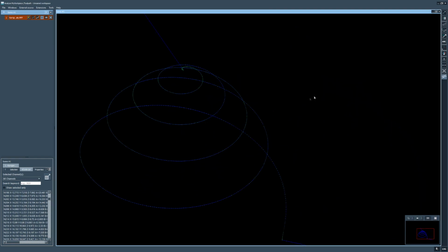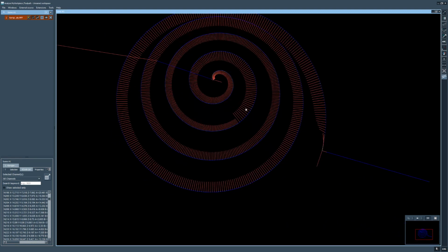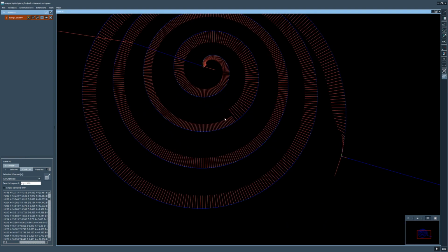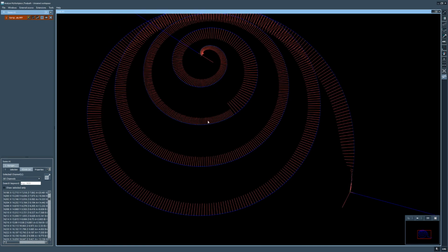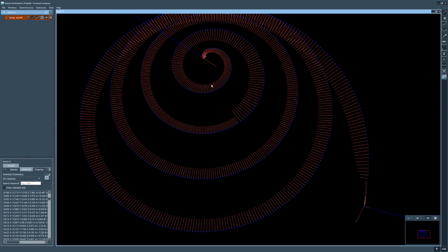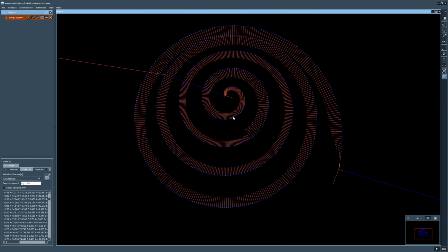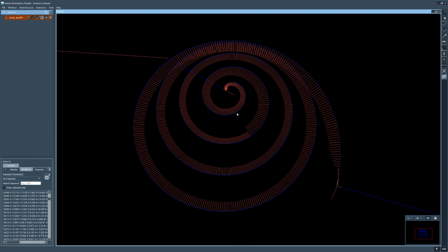The next button we have here on the right, below the tool orientation, is the curvature. If we click it once, we see the curvature for the whole scene. For each point, the curvature can be calculated using the edges and points. The curvature actually reveals very important information. It will tell you how smooth the movement of your mechanic will be by following this toolpath.